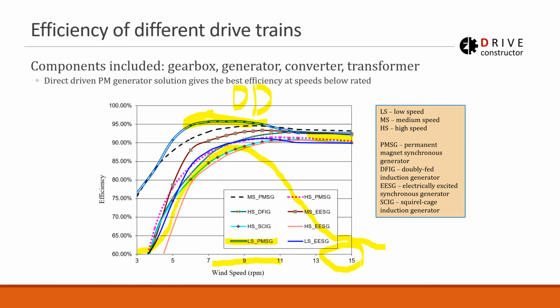So then direct drive is really good choice here and for this particular case. And actually direct drives are more and more used in wind turbine industry. So like 20-30 years ago, usually they would have a 3-stage gearbox with an induction generator, but today it is more like direct drive with permanent magnet synchronous generator the wind companies would use.